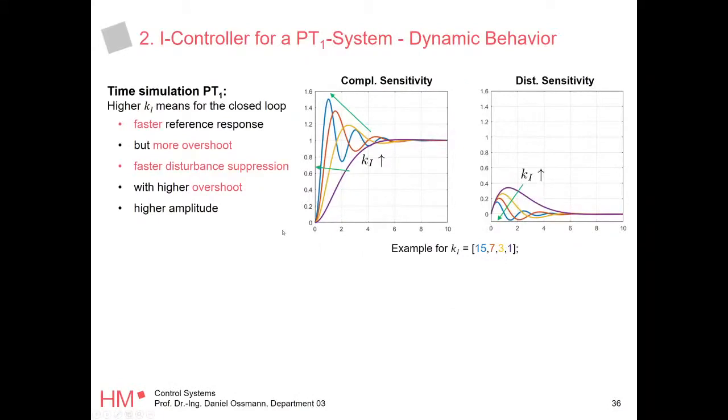So what happens to our proportional system of first order if we close the loop? What we see is that this guy always gets to 1, right? So we have steady state accuracy because of this integral in our system.